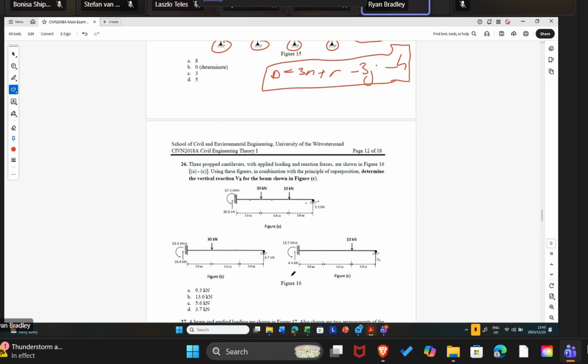So I could ask you for any parameter here. I could ask you, what's the reaction force in any point in here? Or any internal force, it would be the internal force here plus the internal force here. What's a reaction force here? Simply reaction force here plus reaction force here. And the same is true of deflections. If I give you this problem and I give you a deflection over here, that deflection will simply be the addition of that deflection there plus that deflection over there.